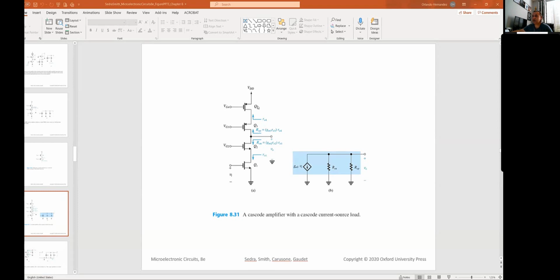And those are Q3 and Q4. So now I have 4 transistors so far in my basic gain cell. And again, the actual signal input is coming into the gate of Q1. That's the one actually doing the amplification. The other ones are just constantly biased. And I generate VG4, VG3, and VG2, again, with current mirrors and current steering, which we discussed at the beginning of the chapter.